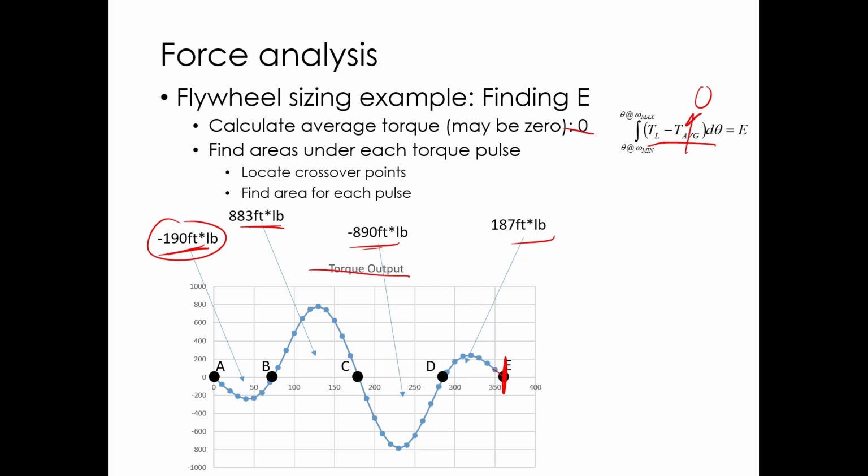Remember, foot-pounds is the unit of energy in crazy US units. So how do I get pound-feet to foot-pounds? I need to multiply torque times theta, where this is in pound-feet times radians, not degrees. And then I get foot-pounds of energy. For those of you that are used to metric, I'm sorry, but that's what we have to do. It kind of works like that in metric. It's got to be Newton meters times radians, and they just have a named unit, the joule. We should have a named unit for energy here in the US. I don't know why we don't.